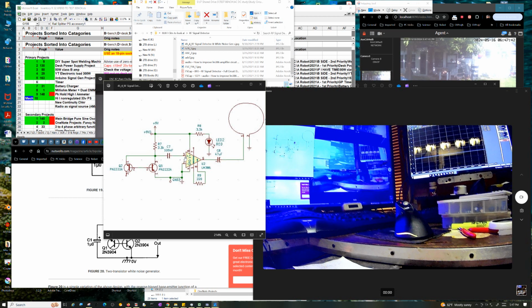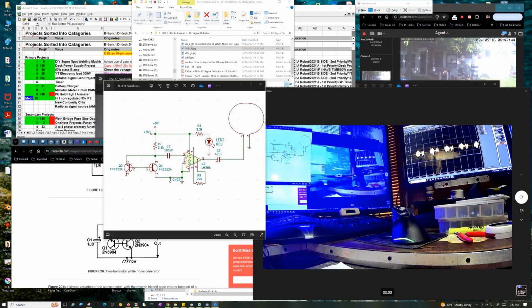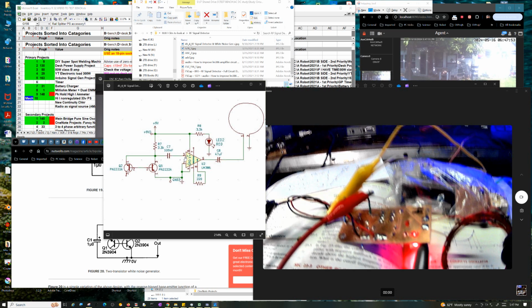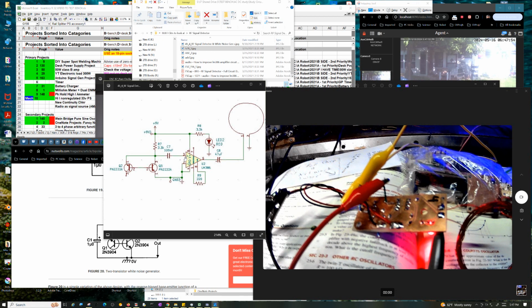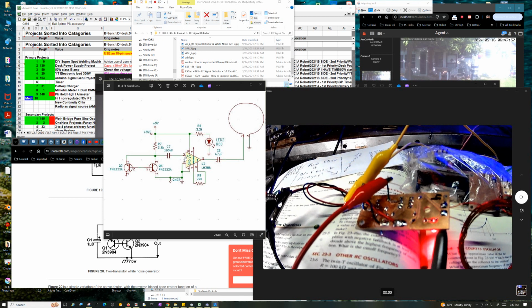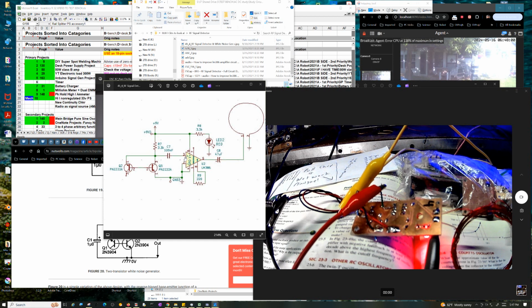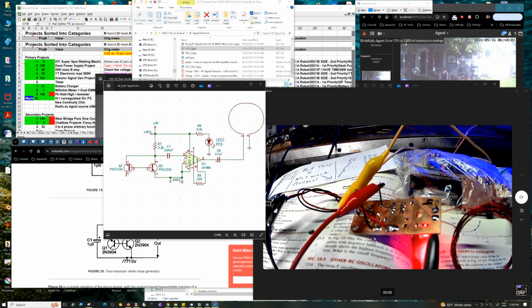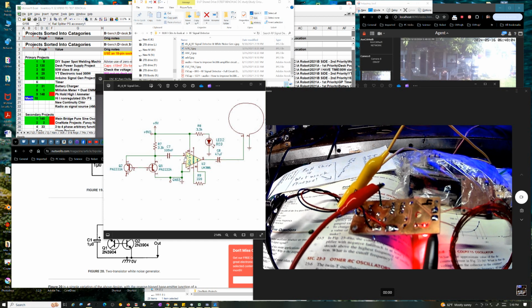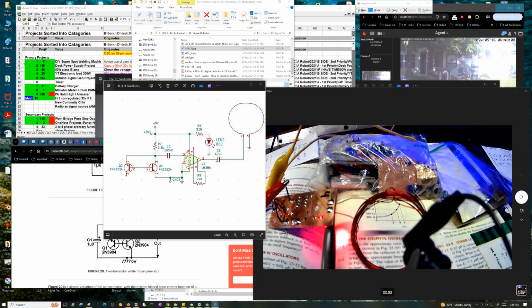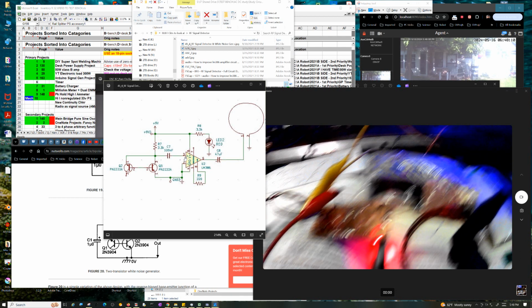In fact, you can make one like mine that has a noise source on it, but you can also put a pure waveform into it, because basically I'm applying a pure waveform directly to the input of this 50 kilo ohm LM386. Because it's supposed to be AC coupled, I'm just directly injecting it, right? So that's why we're getting not really a full waveform. But this way I am able to inject the noise on.